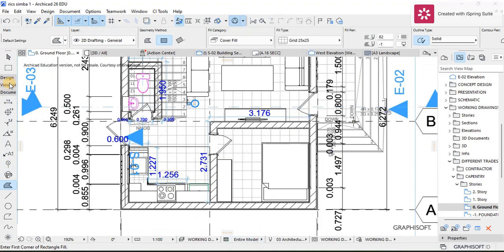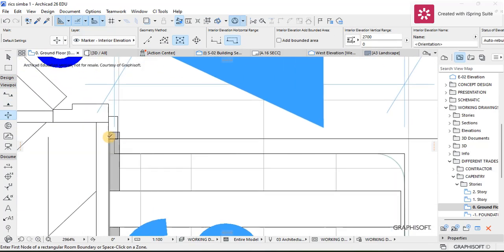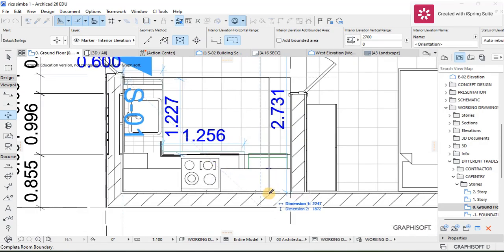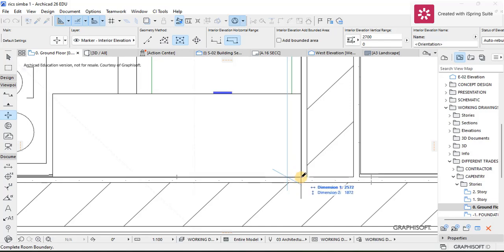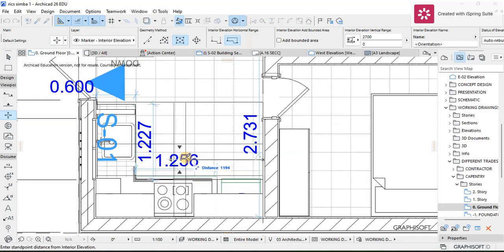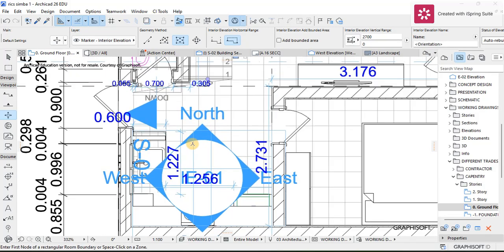So let's go to the viewpoint, interior elevation. Then we're going to draw where we want our interior elevation to cover. So I want it to cover the kitchen in terms of where the boundaries of the kitchen are, and I finish it off by drawing the something like that. So you can see now. Yeah, and from these interior elevations, if we find other information that might concern maybe the tiler, we'll still bring the interior elevations back to where the tiler is.